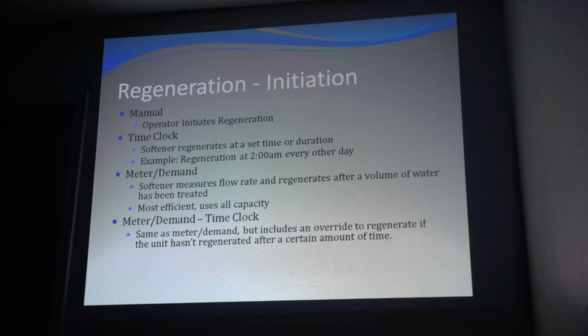For like even tannin applications in a cottage, it's good to refresh that bed even if they're not using the water regularly. Let's say it's set for 1,000 gallons between regenerations. If they're not up there but every 4 weeks, you want that thing to regenerate maybe every 10 days.